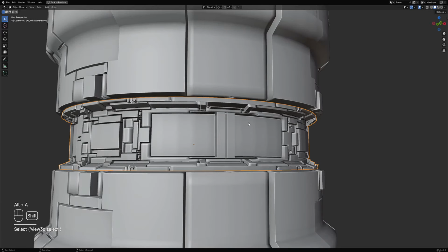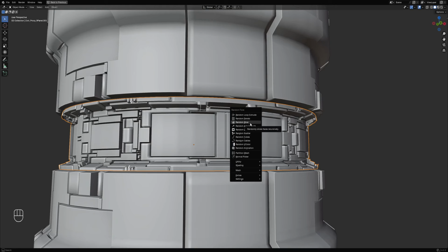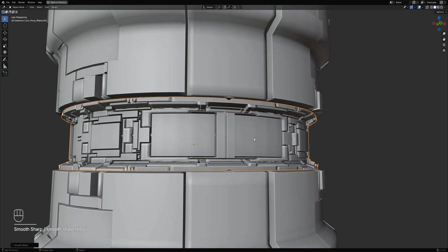And we're going to get rid of subdivision banding. The subdivision banding usually appears for curved and cylinder surfaces, usually at level 2 subdivision, especially when using like 32 to 64 segments in the base mesh. And I mean, when using a lower base, lower, not higher, like 64, but lower, like 32 and 24. Okay, mesh smooth or smooth sharp.